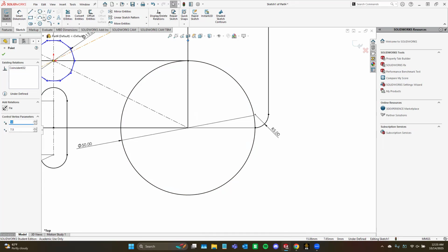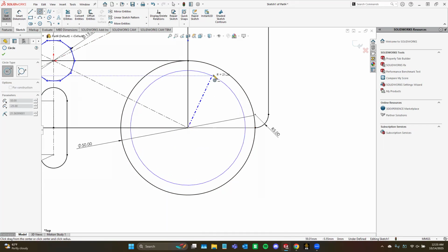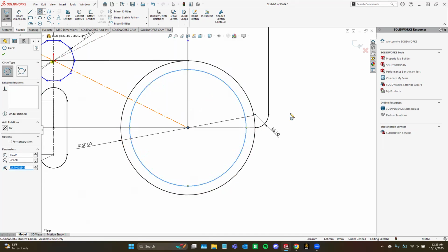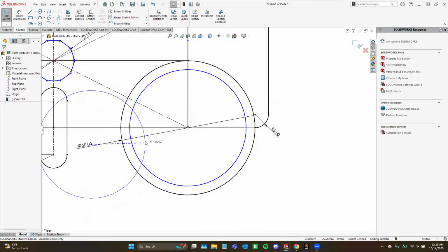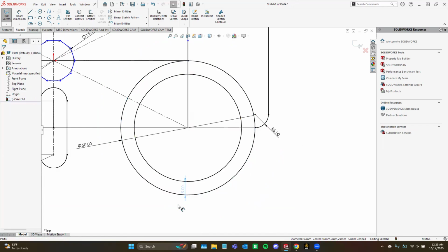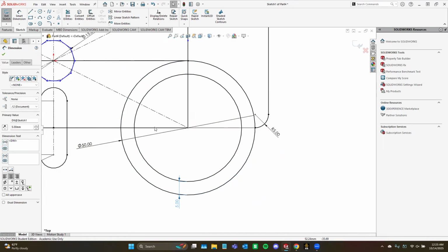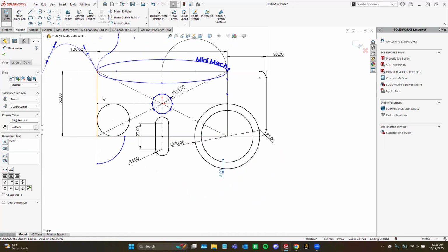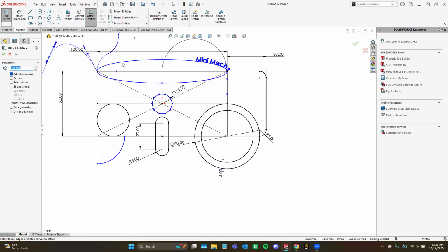Instead of placing a circle and then doing the math, like, okay, this is 50 millimeters minus 10 because 5 on both sides, and dimension that, and all that, you can just go to offset, click on the circle, define the offset you want, make sure it's on the right side. Okay, and you're done. You have yourself an offsetted thing, and it works on everything. So it's pretty cool.